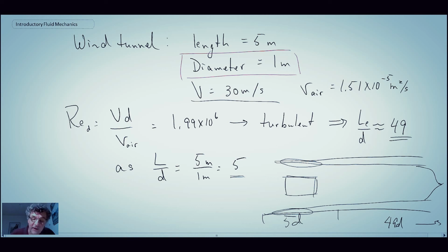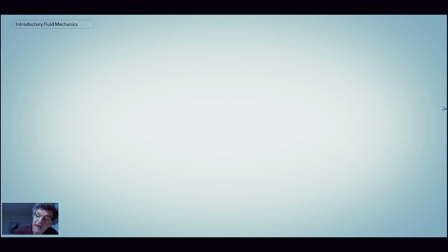Now, in other cases, you might be doing things such as flow metering, and if you have a pipe and you have your entrance region, and then let's say you're going to put an orifice plate meter. That's a way that we measure sometimes volumetric flow rate. We get P here and P here, so we're measuring a delta P across the orifice plate, and then we have a vena contracta coming through. But they're calibrated. We can figure out exactly what the flow rate would be based on the delta P measurement.